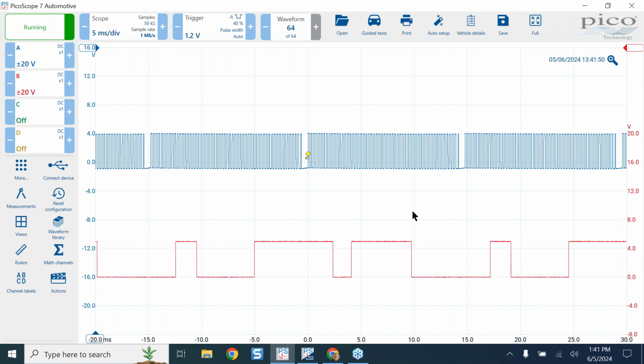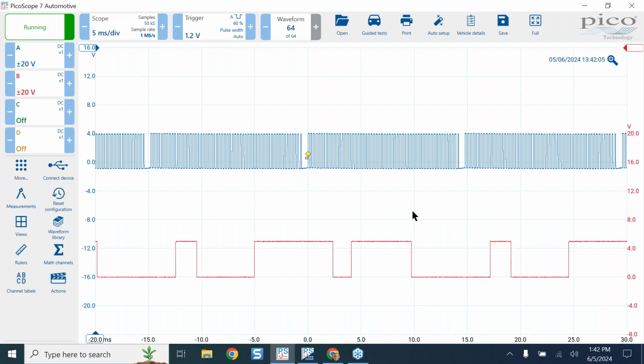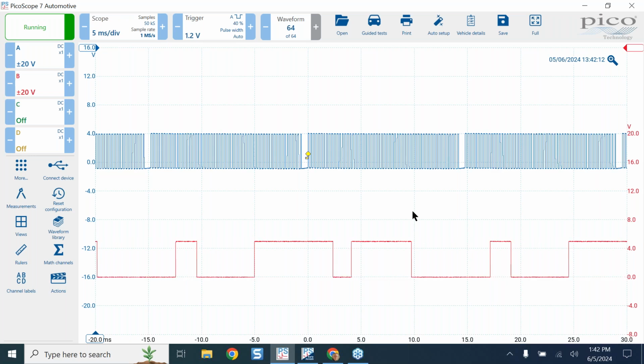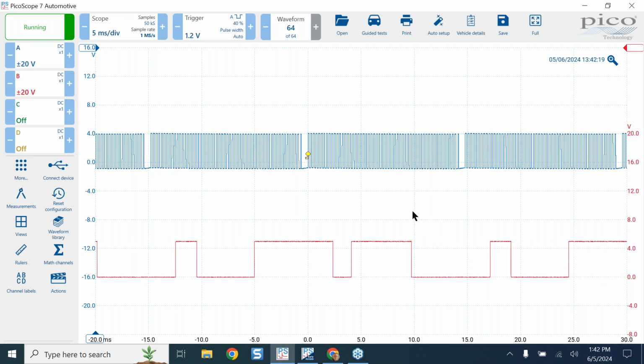We all know the crank is 360 and the cam is 720. So one revolution of the crank is going to get you, you don't know which the orientation is for cam encoding. So you're almost always going to trigger off of your cam encoding, especially if it's an encoded signal. You're always going to want to start on the cam, not the crank. I just did it because my crank happened to be on channel A. So in order to trigger this cam crank properly and to look at the encoding and to make sure, do we have a signal issue, a signal integrity issue?